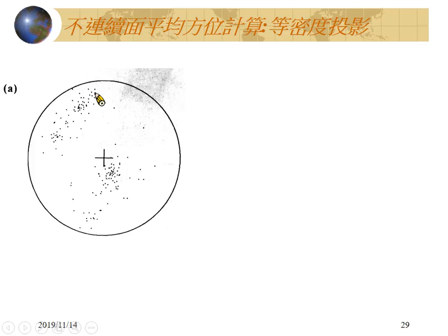So if the normal vector is here, you will have a great circle roughly here. So it would be north to the east, roughly 60 degrees, and dip to the northwest, roughly 30 degrees.